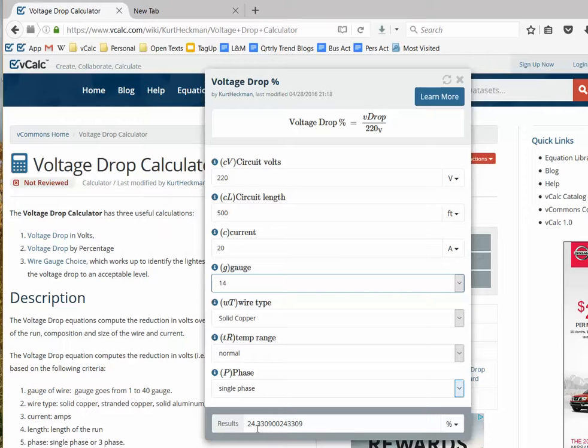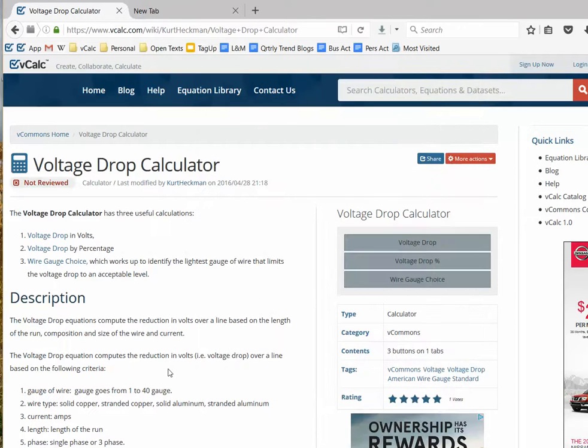What you find in a lot of equipment is they're very sensitive to that. This will burn out motors, etc., if the voltage drop is more than just, sometimes it's 5%, sometimes there's a 10% threshold, but you have to look at what the manufacturer's gauge is. So that's one thing to calculate, very useful, again, a free calculator here.